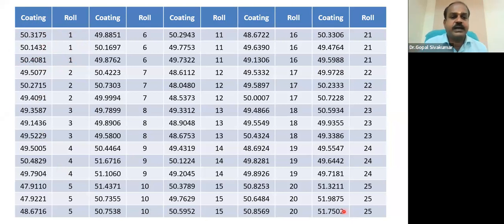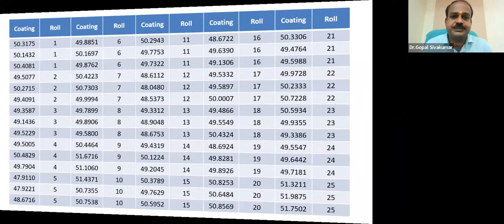With the 75 data, you need to calculate Cp, Cpk, and you need to calculate Pp, Ppk. Now, if you use the data in a particular manner, you get Cp, Cpk. If you use the data in a different manner, you will get Pp, Ppk. But the data is common. All of you are with me? Now, there is within capability and there is overall capability. Let's see how the calculation goes.